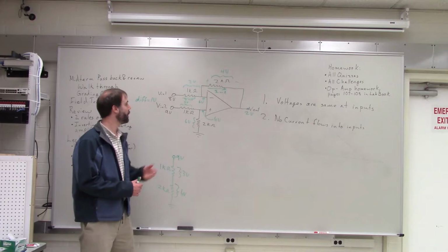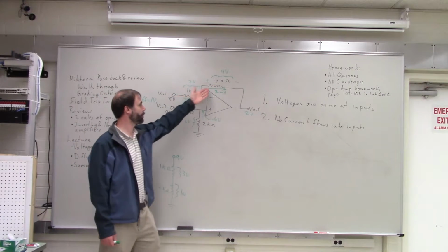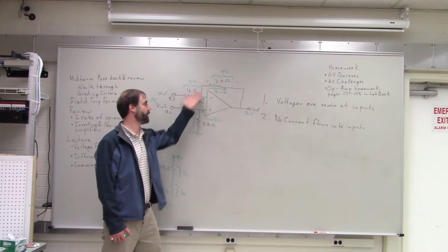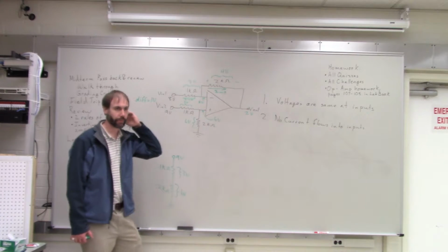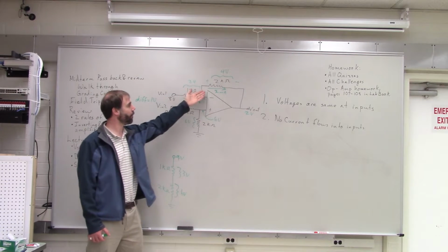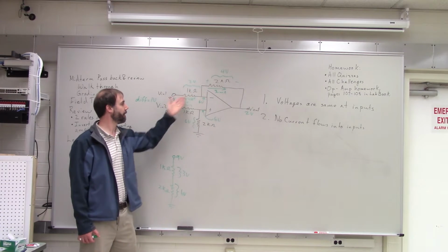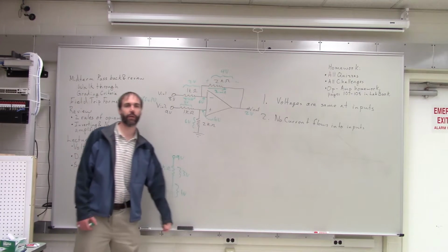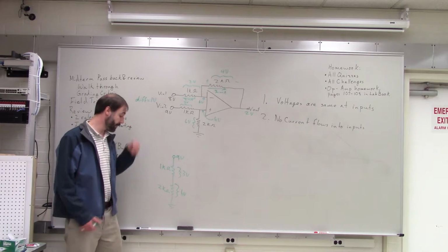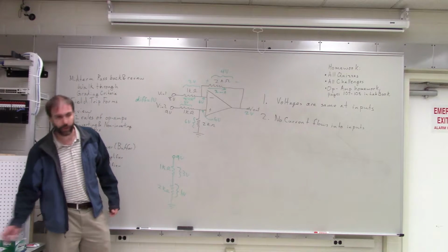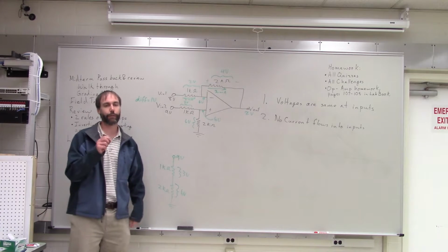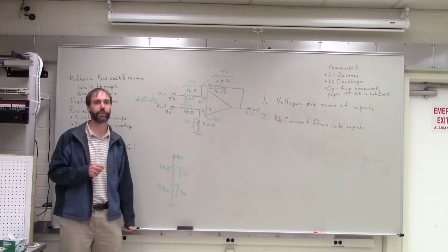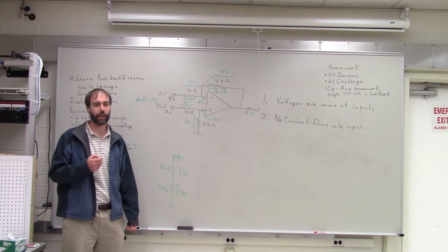Okay? So we could set our gain to be higher by choosing different resistors here. We could choose a gain of 10 or a gain of 100. And then we could multiply the small change in input by that gain. Okay? So this is really an important circuit for measuring the difference between 2 signals, especially a small difference between 2 signals. So you could use this for things like an EKG.